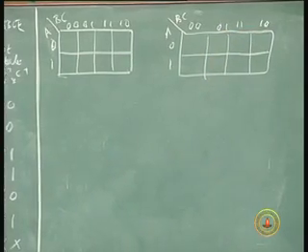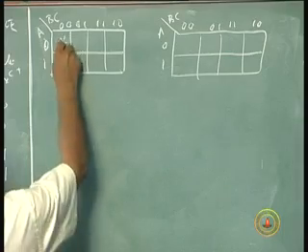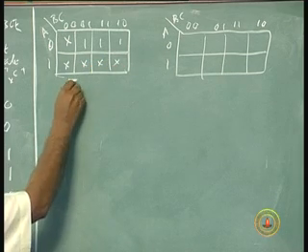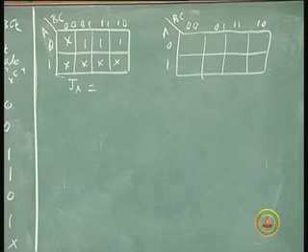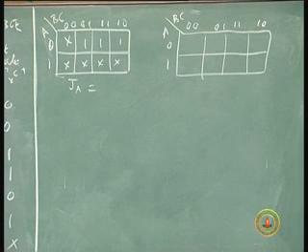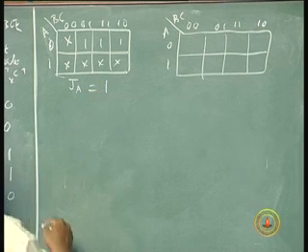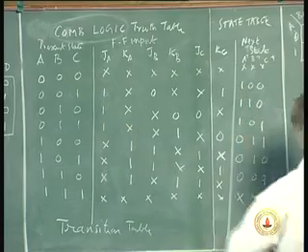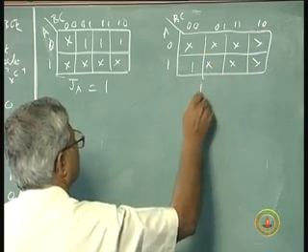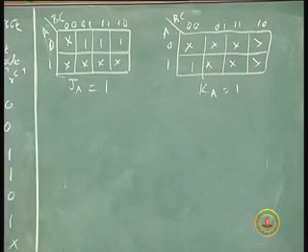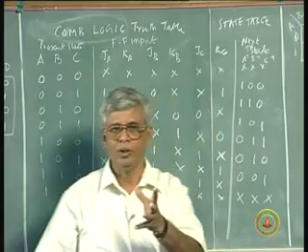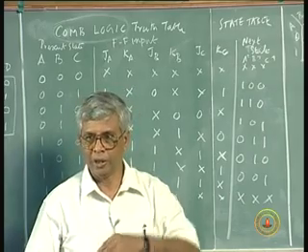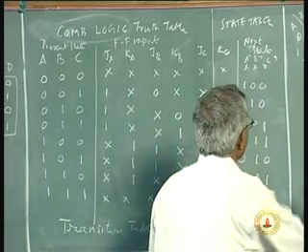So, we will map this JA, do not care 1 1. This is JA map. What is JA? Value of JA is 1, all do not cares can be assumed as 1. JA is 1. KA map will be all do not cares, all 1. That is what I meant when I said the JK flip flops' steering logic will be simpler, even though there are 2 inputs each time, because at least 50% of them are do not cares.